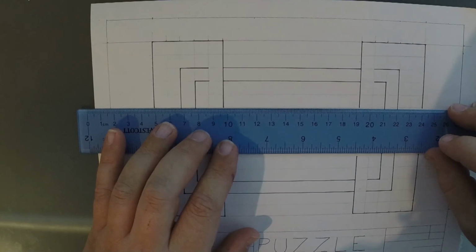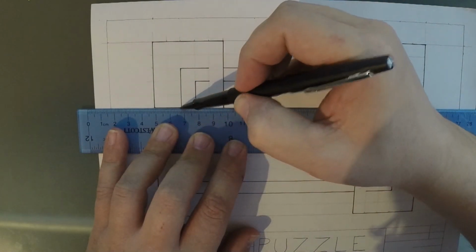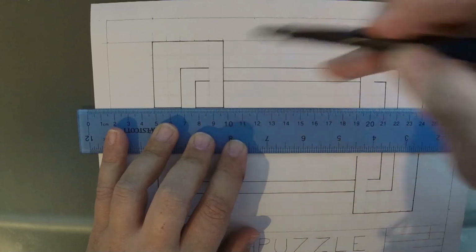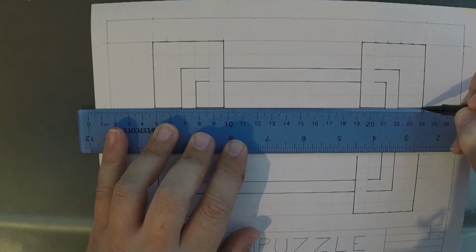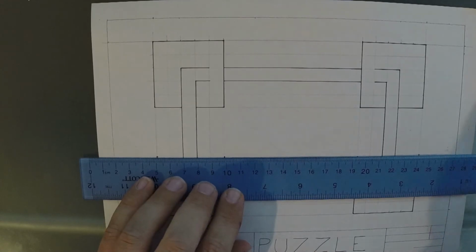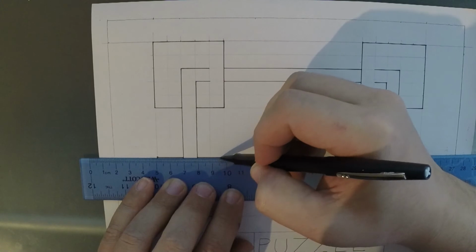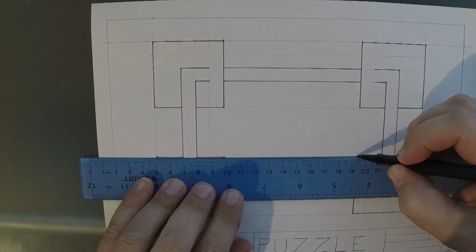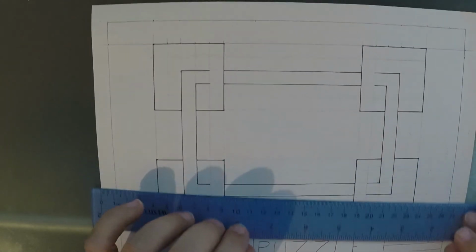Okay, now that I got those columns in, it's a little bit easier to find the top and bottom of each of the pods because they're stopping right where those are. So you're using object lines. A reminder that an object line is a normal weight line. It's darker than those construction lines on the page, but it's lighter than your border and title block.